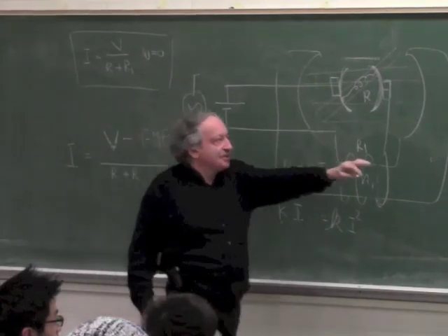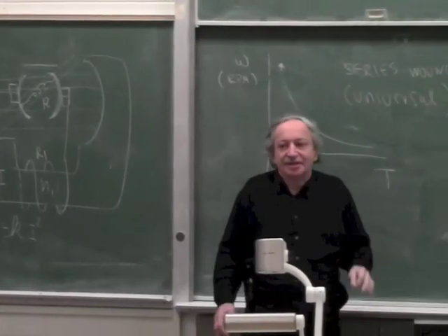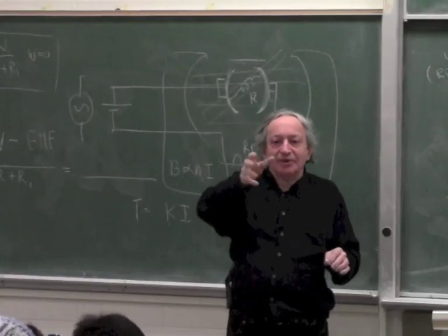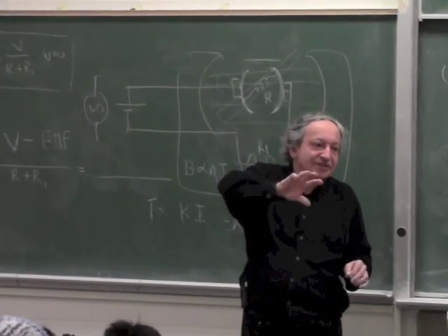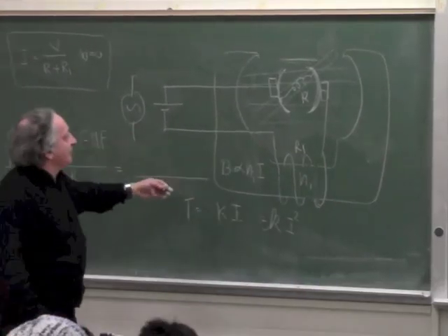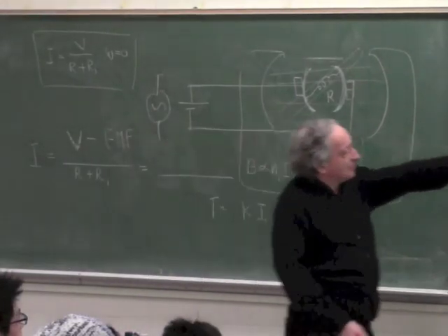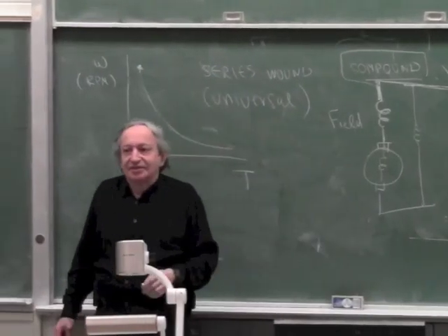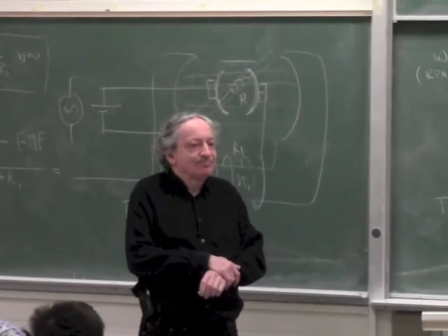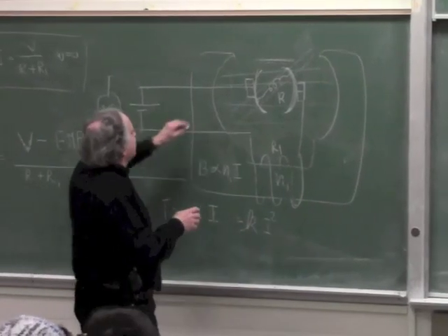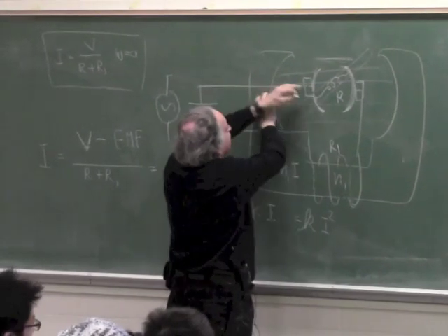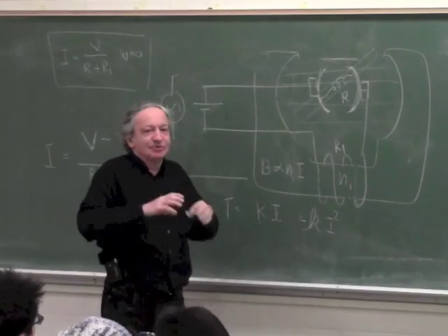In PMDC, just as a reminder, we already decided last week that it wouldn't work with AC, because on one half cycle it will try to turn one way, on the other half cycle it will try to turn reverse, right? So it just vibrates, okay? But what will happen in this motor, which is the same motor, if we applied AC? Will it rotate or not? Yes, and why? Because both switch together. If this is N and this is S and they attract, if the cycle reverses, this will be S, this will be N, they still attract. Because they're in series, they both switch together.